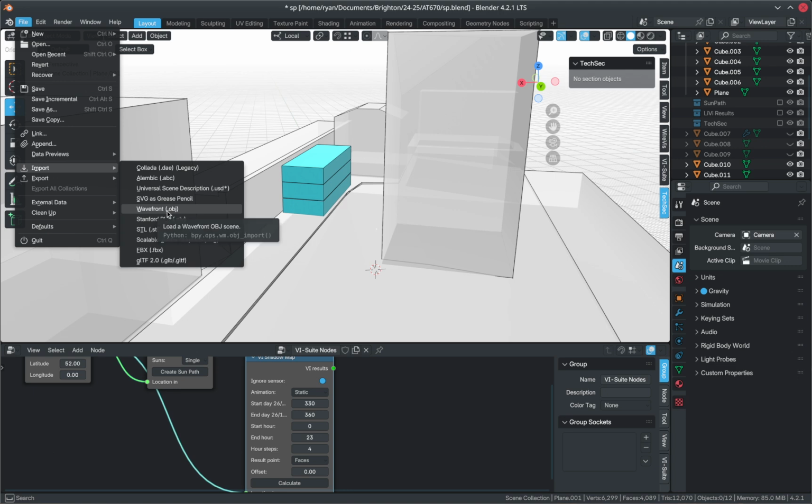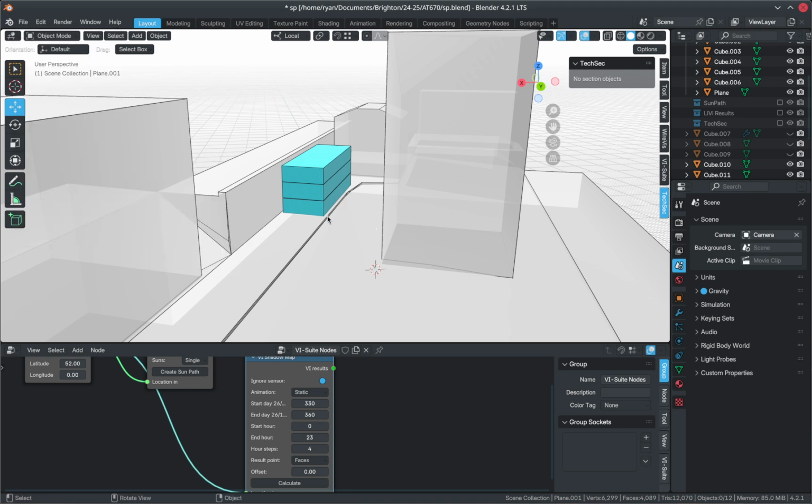When you import OBJ geometry, there are a couple of things to look out for. If you modeled it in a package that was using millimeters, then when you import that model into here, it will be massive because Blender will interpret those millimeters as meters. So if you're modeling in Rhino or wherever, try and remember to model in meters. If you forget to do that, there's something we can do to correct it, but just to make life easier, try and remember to model in meters.